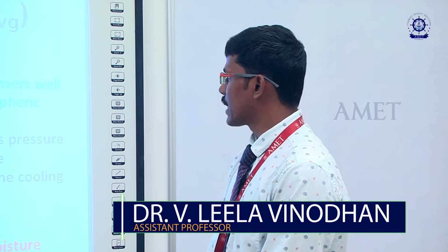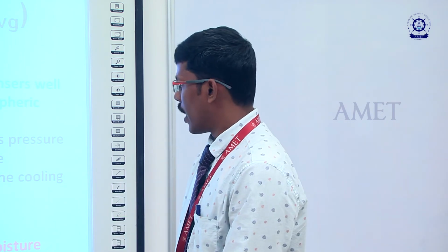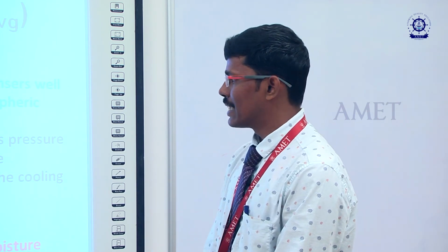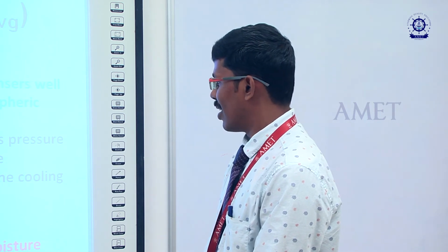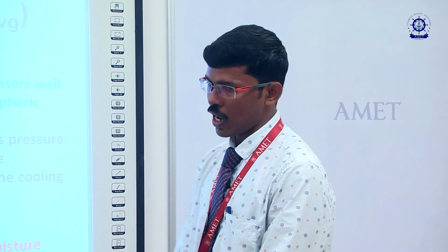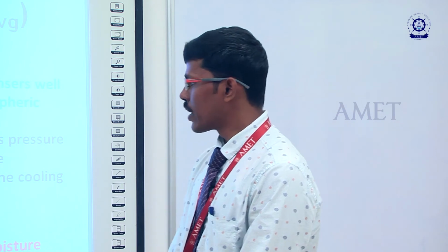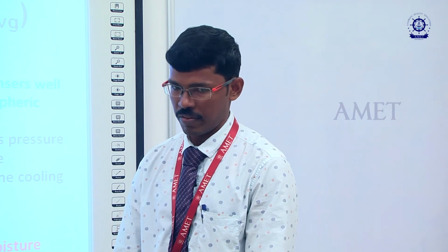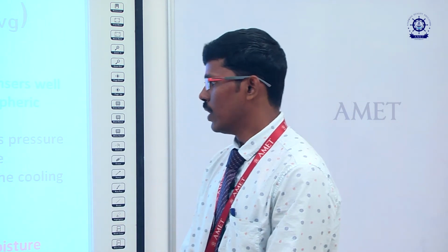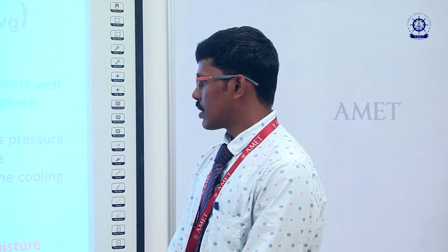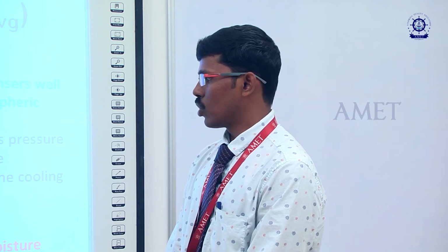The condenser can be operated at a lower than atmospheric pressure. But this is limited by the cooling medium in which we are working, because we require a certain temperature difference, and moreover that should fall within the saturated pressure value. Lowering the condenser pressure also increases the moisture content of the steam.